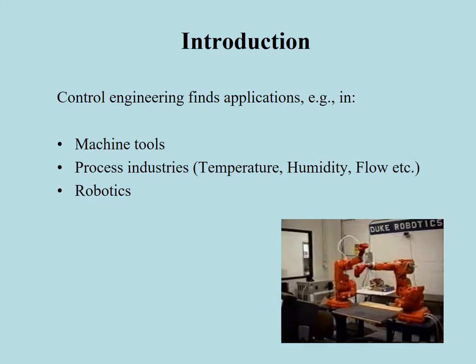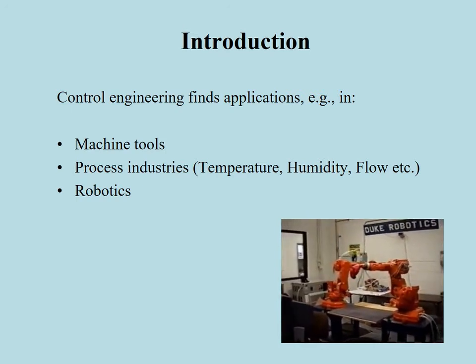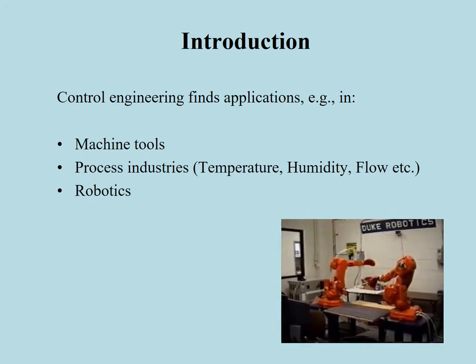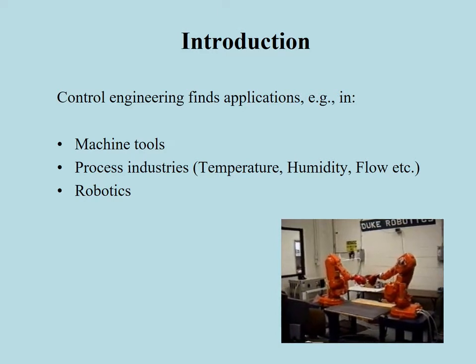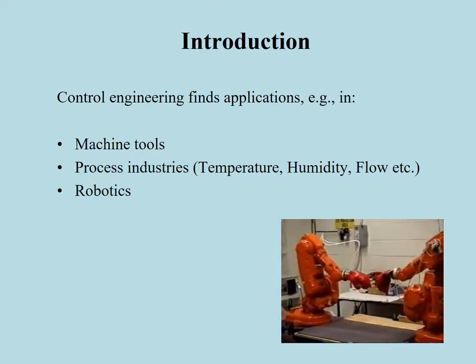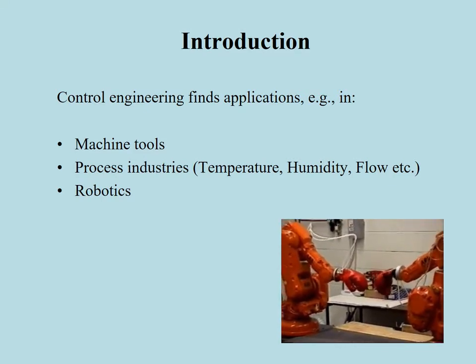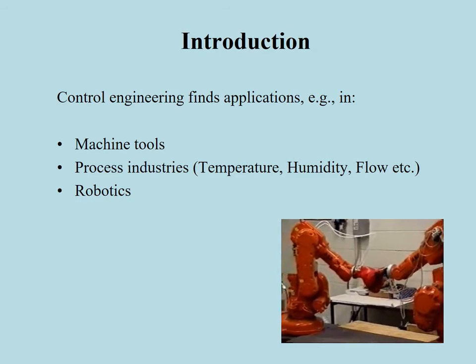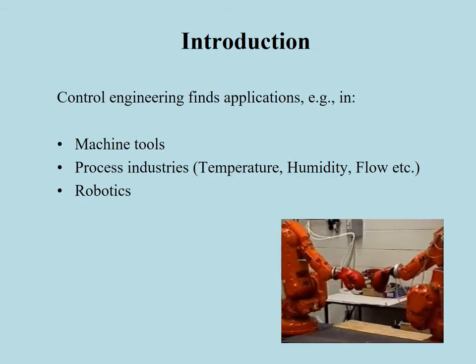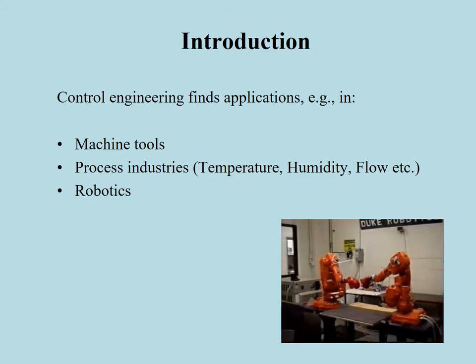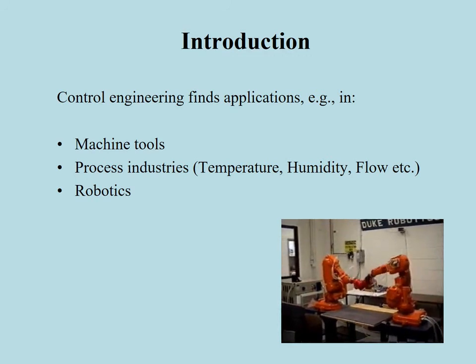Because of the excess degrees of freedom, an end effector position does not directly translate into a unique set of link angles. This problem is known as the inverse kinematics problem of a robot arm, and in determining the angles of your motors, you have to choose the best of the possibly infinitely many solutions.